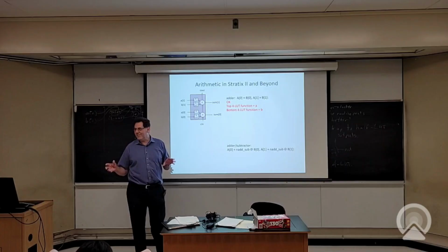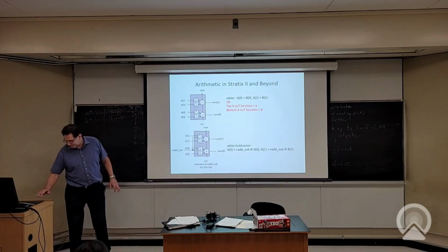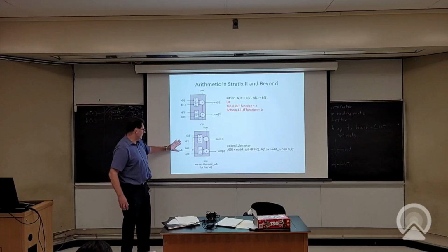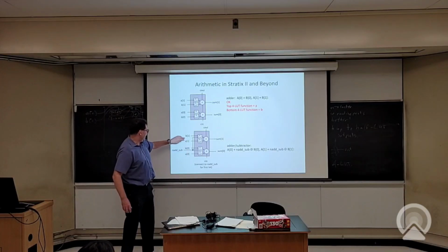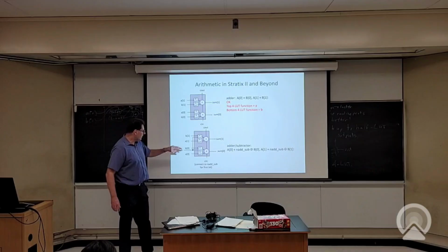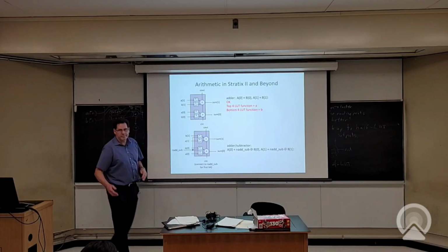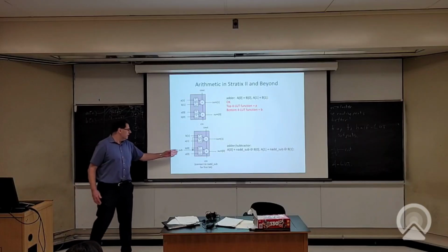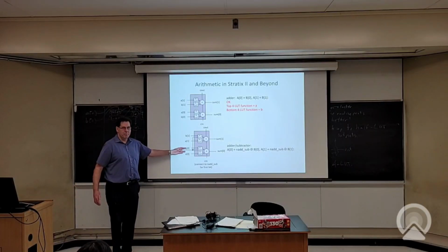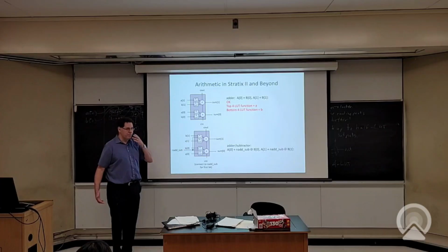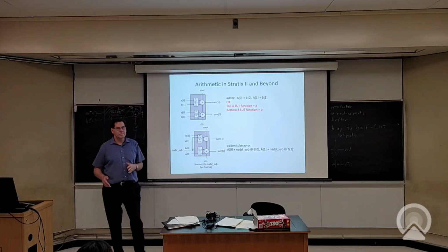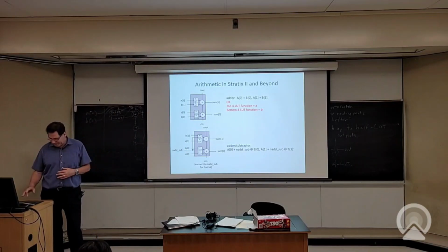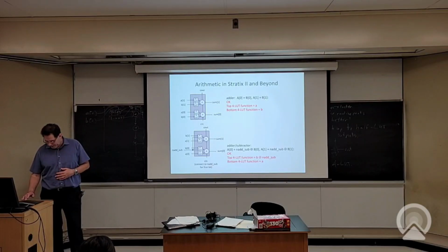So I see Alex says yes. Okay, so let's check. Basically in the LUT functions, yeah, I can do all of this. The lower LUTs here are just doing copying through A. The upper LUTs are a function of a bit of B and this n adder sub. So that's only a 2 input function. That's fine. I've got 4 LUTs. And if I count all my inputs up, I've got 1, 2, 3, 4, 5. 5 is less than 8. So it all works. Okay, so that looks good.